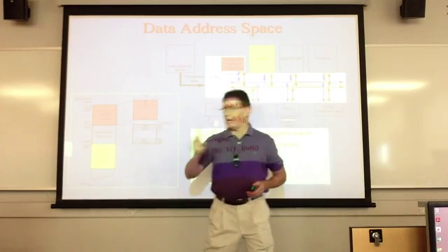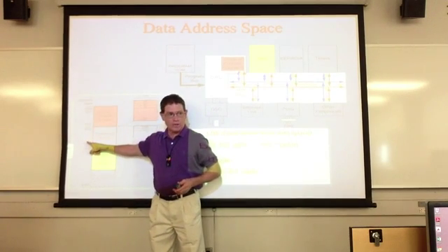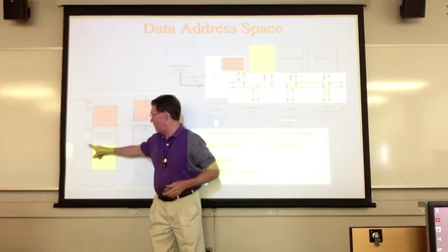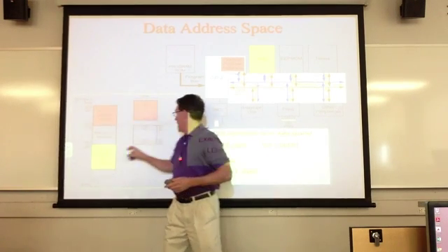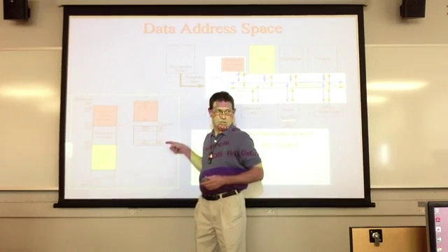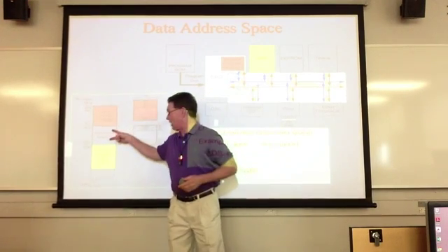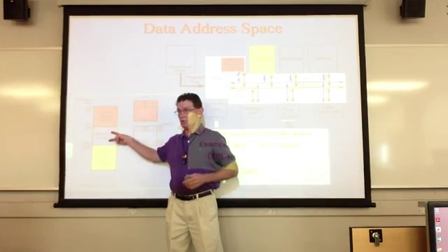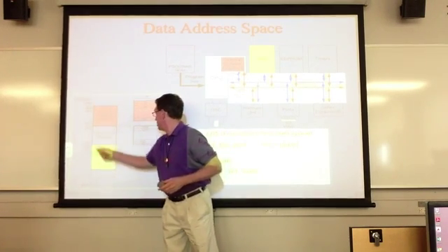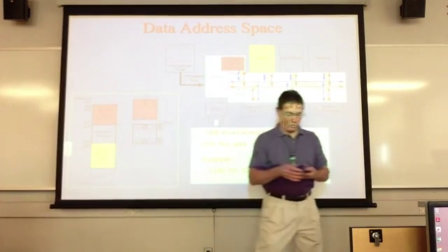There's two kinds of addresses that go on inside of here. There is the physical address. In his case, it goes from 0020 up to 5F. And if you'll notice over here, there's something called the IO address. So each one of these guys in here physically has two addresses. There's one, which is the data address space, and then there's what's called the IO address. And we'll get to this down the road a little bit.